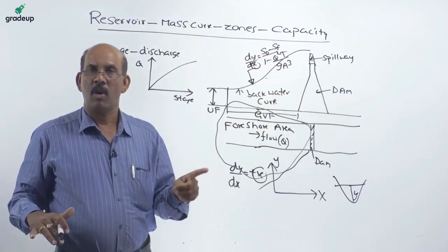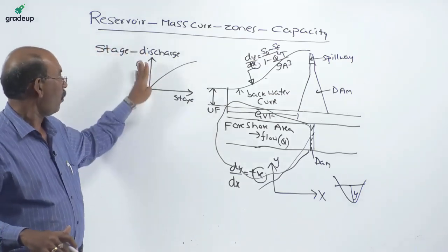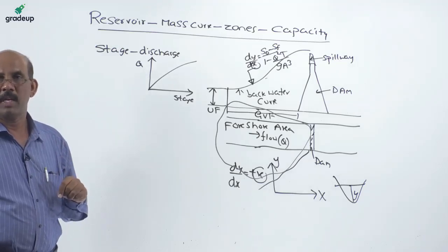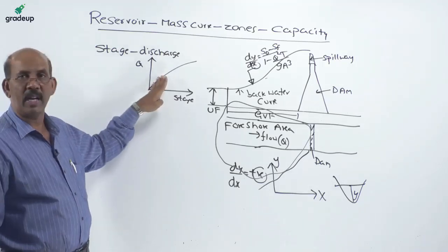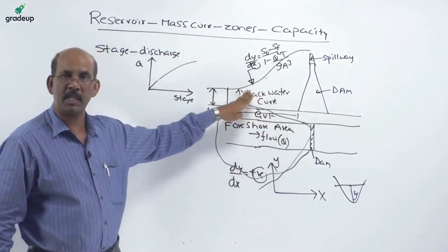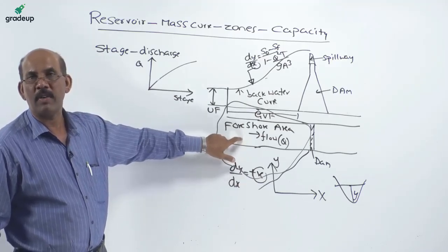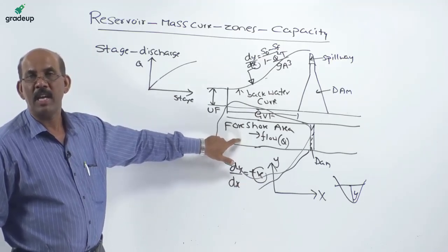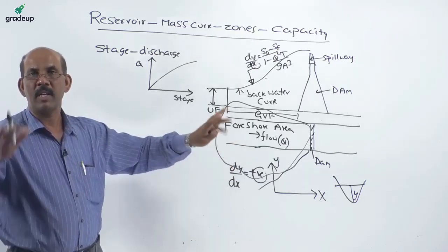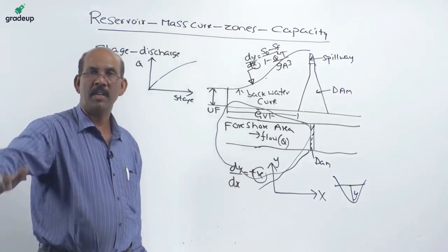Now we want to calculate the discharge, or we can say the volume. This is the available flow, and at the location where we are constructing this reservoir, we have to see the ground level, how the valley is, and what is the maximum volume of water that can be stored, from our surveying, that is plotting the contours and developing them.